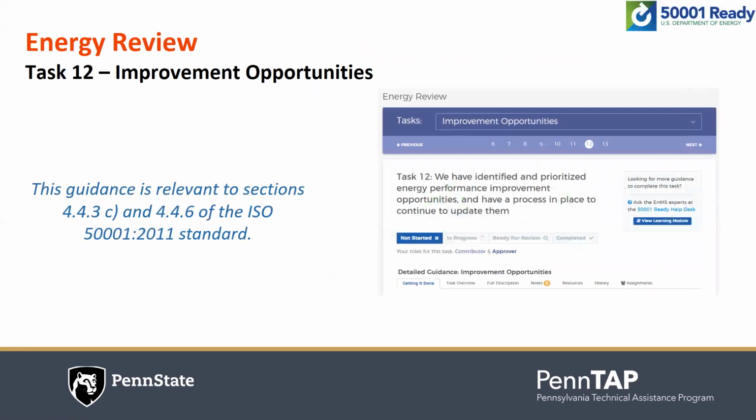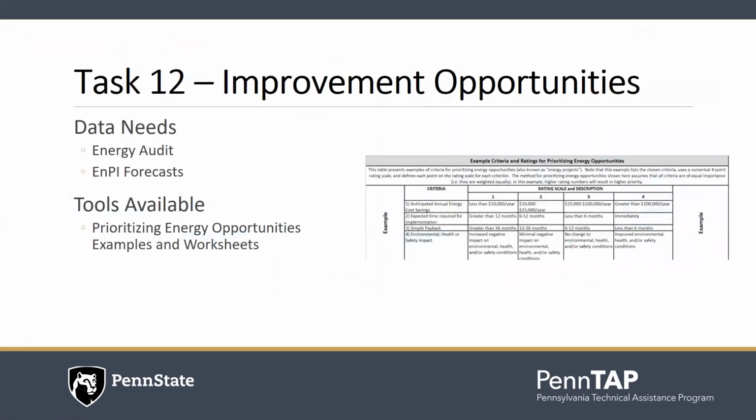So next up, you'll take a look at what the improvement opportunities are. Now I'm going to stress at this point, you'll want to go through and do an energy audit. You could have a third party come in and do it, or work with your energy team to develop those improvement opportunities. And this includes both big, large improvement opportunities such as replacing your boilers, but it also includes smaller, simpler reductions. For example, it could be as easy as changing out thermostats to be more accurate, or going around and lowering the thermostat from 70 degrees to 60 degrees.